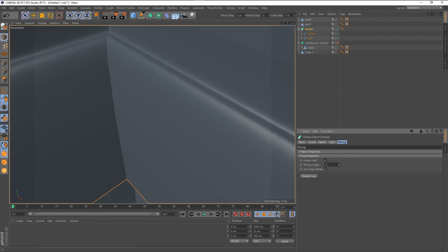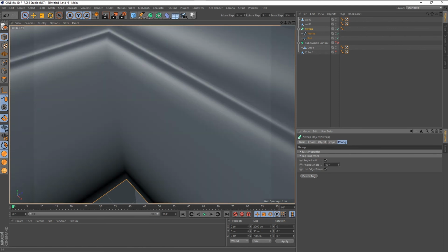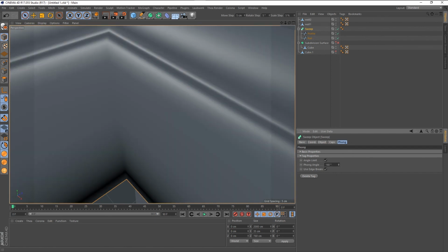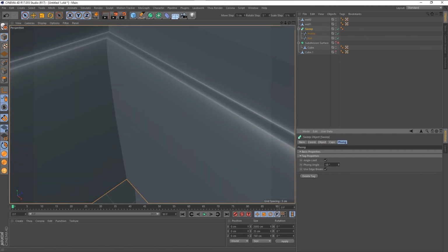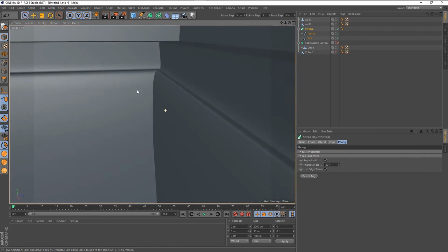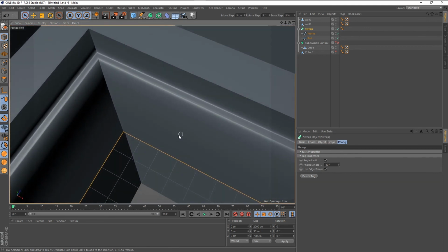You can change this setting. This is smoothing everything, this is smoothing nothing. So 0 is no smooth, 180 is everything smooth, and the default was 60. I would set it to something like 40 maybe. Seems to look pretty good.